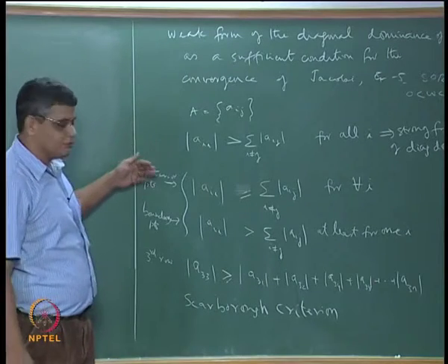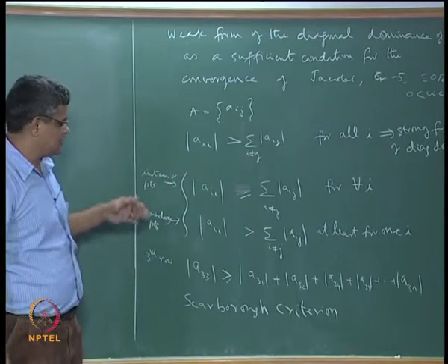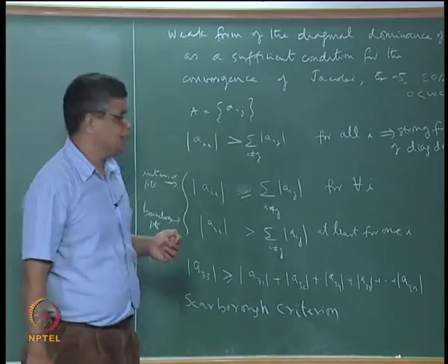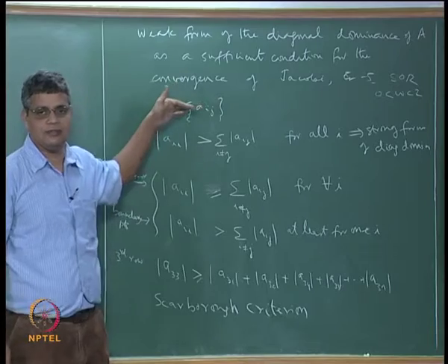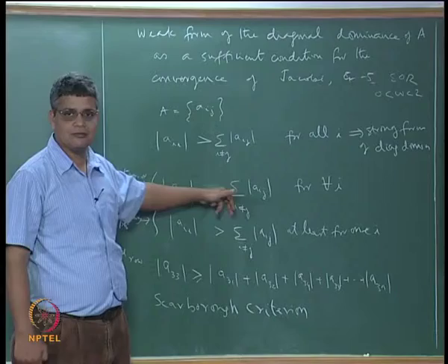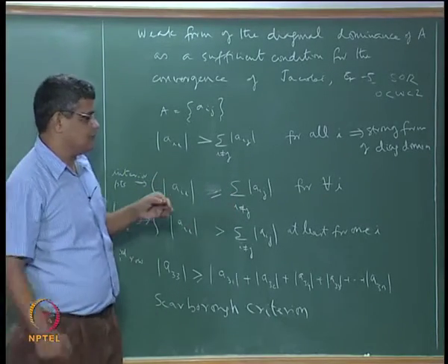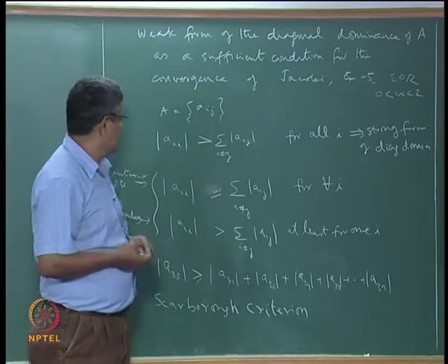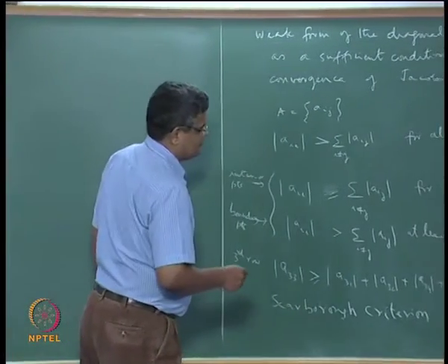So for diffusion problems or for unsteady diffusion problems, we can rest assured that this will be satisfied without a source term. But if we have a source term, then depending on whether or not the source term depends on the value of phi, we can either break this condition, or we can still honor this condition. So that is why in the discretization of the source term we have to be careful. For example, if you have a source term which is